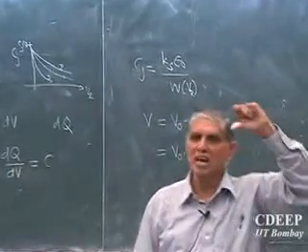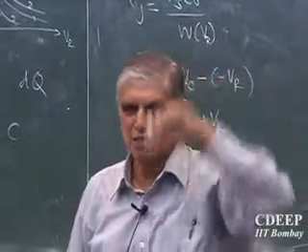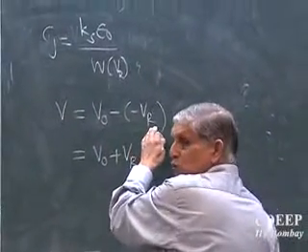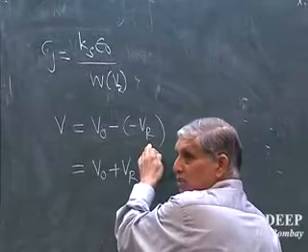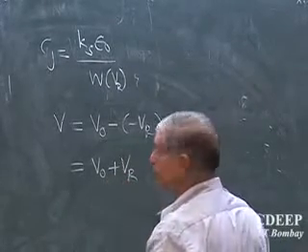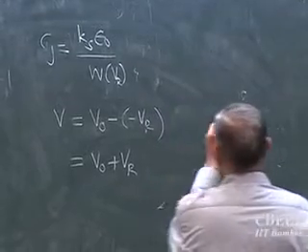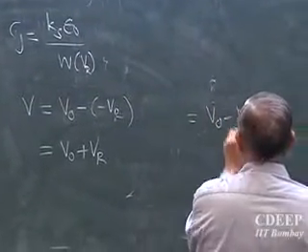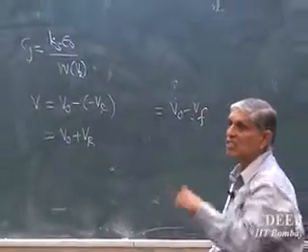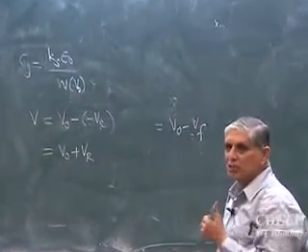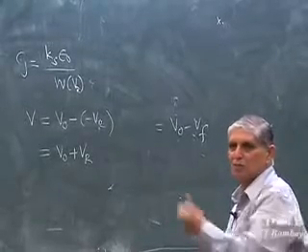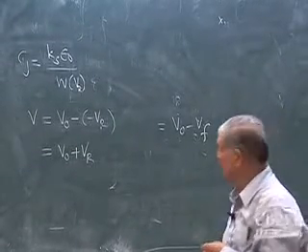So they will actually add the voltage. Is that clear? So this was the initial voltage, this is the new voltage, additional. This is the actual difference you are getting, but since it is negative, it actually adds. In the case of forward bias, what will happen then? This will be V0 minus VF, because that is a positive sign, so it will actually decrease that value. Is that clear? So the difference of voltage is additive or subtractive, depending on the sign of V.